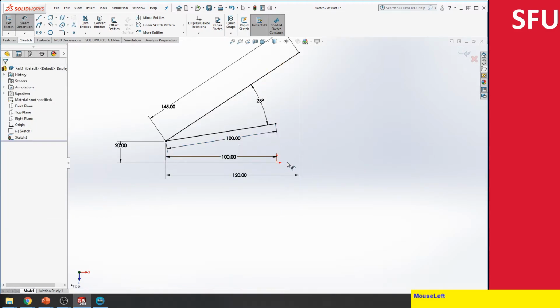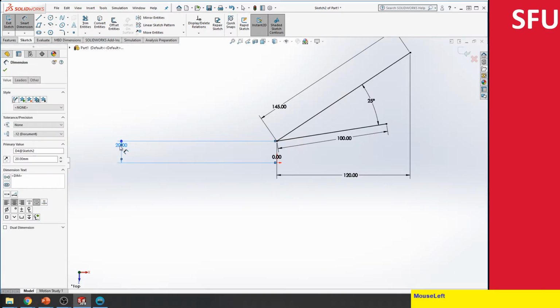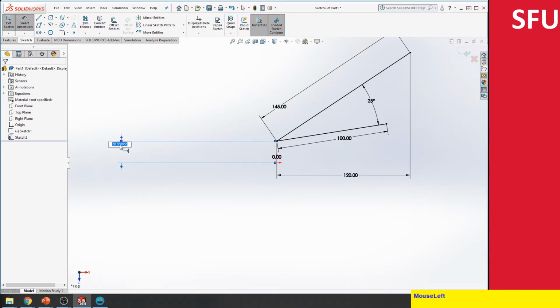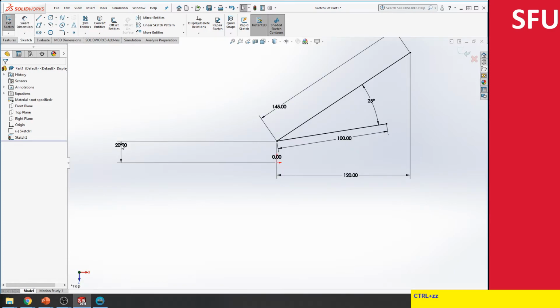For instance, I set the distance of this point from here to be 100 and the height to be 20, right? If I wanted this point to lie exactly here, one way I can do that is basically set this to 0 and then set this to 0. I double click on this and then I set this to 0, and that ensures that the point is exactly aligned with that origin over here, which could be potentially tedious because you might have to make multiple or a lot of constraints like as such.